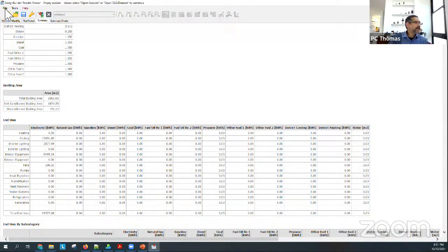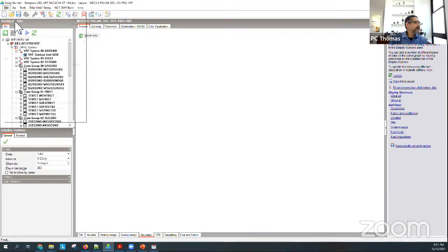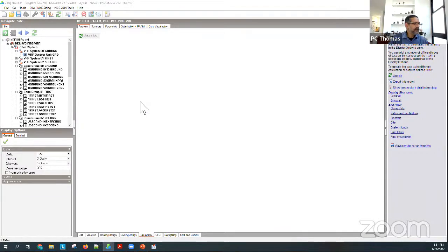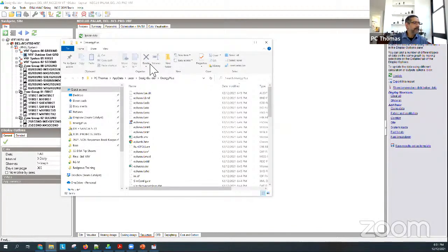Now, if you remember, I told you that if you go to the File and the folders in DesignBuilder, in the EnergyPlus folder, all these results will be there. And you can pick up all the files from here. So there's that HTML file. There's a CSV file, which is exactly the same numbers. You can put them into an Excel sheet. The ESO file has got all the hourly results, which is what we're looking at.